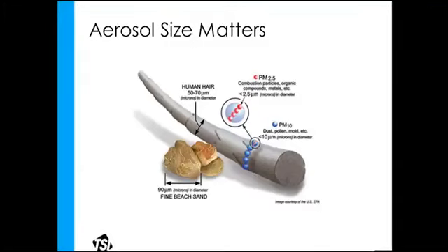So the blue balls are getting down to what we're thinking of aerosols. So those blue balls represent PM10, it's particulate matter 10, and that's 10 micron diameter particulate matter. So if you're measuring the PM10 for outdoor air pollution, those are the sizes of aerosols you're looking at. So we look at this graphic, there's 5 of those spheres of PM10 will fit into one follicle hair. And then each of those blue balls has 4 red balls in it, and that's PM2.5. So PM10 is stuff like pollen and mold. PM2.5, those are the ultrafines. That's getting into combustion byproducts, metal fume, and those are getting pretty small.